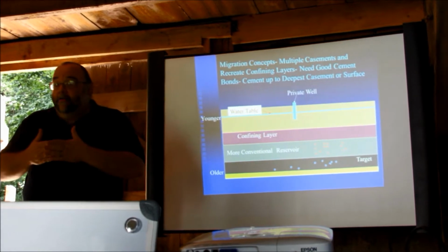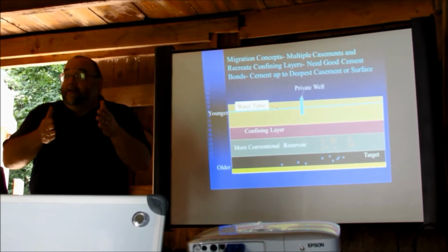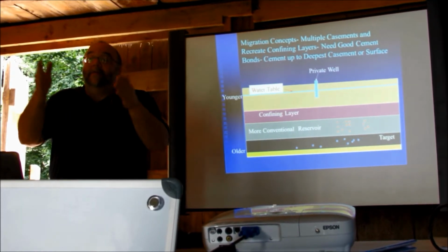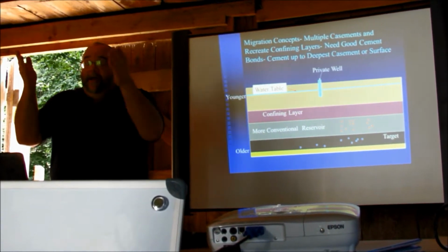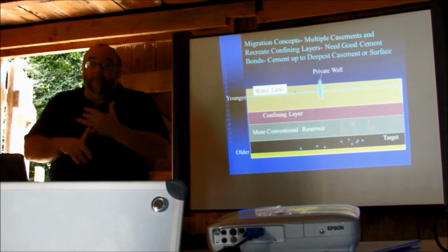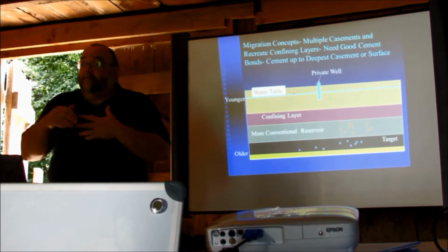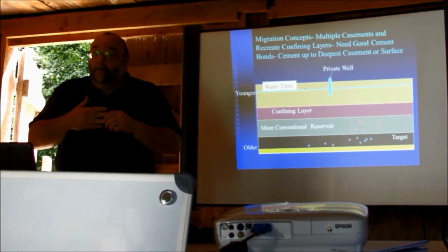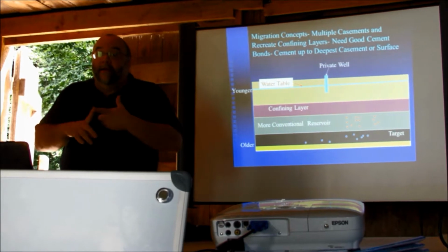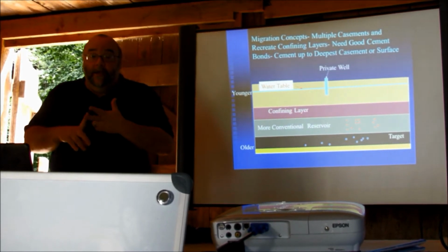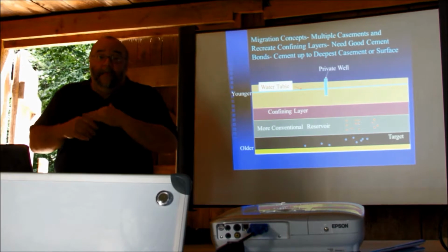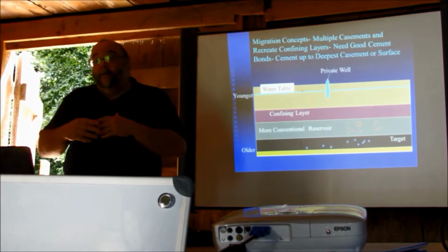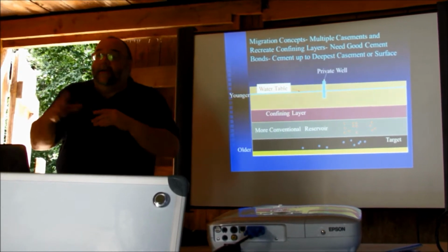So if you're a shallow well, located right near where the natural gas drilling site is, and near the pad, then you should do more and we provide that recommendation, like radium 226, 223, 228, uranium. We do recommend radon. And how many uraniums do you test for? Well, at a minimum, we recommend the radium 226 and 228. For uranium, we'll recommend alpha and beta, even prior to that, because they're actually cheaper. And what about thorium? Usually not, again, but you can.